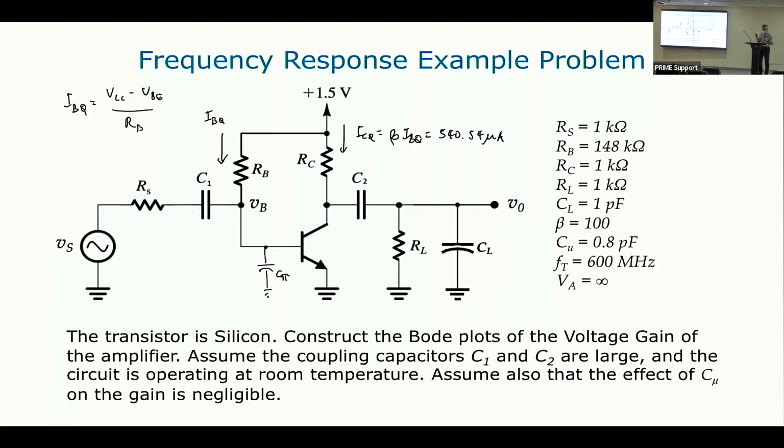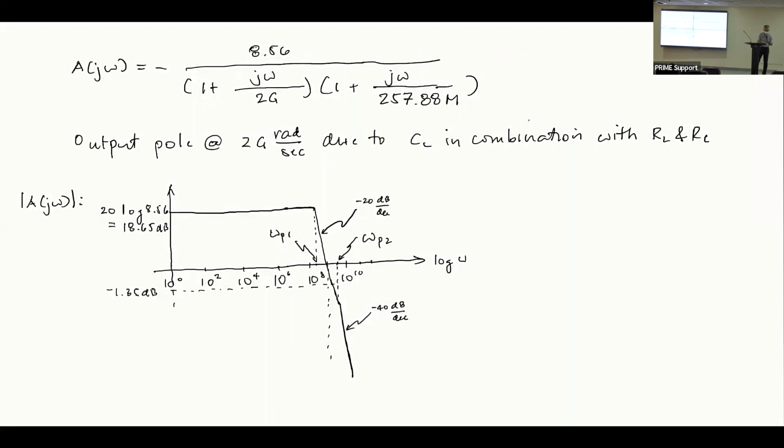Now, the other thing that I wanted to mention is, ano ba talaga yung effect nitong capacitors na to. This will have effect at very low frequency. Okay. Now take a look at this. No? So this is supposed to be A(jω). This is supposed to be my gain, and my gain has a certain value at DC. No? Well, this is not DC. This is a frequency of 1, because you cannot show a frequency of 0. You cannot show a frequency of 0 pag log scale.